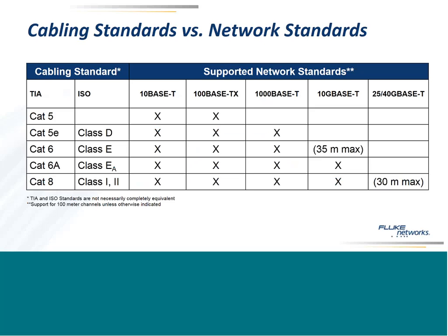It shows you the cabling standards. Now, as I mentioned, ISO and TIA generally work pretty close together. The standards I've put here on the same row aren't exactly the same, but they're pretty darn close. And for most people, you really don't need to notice the difference. So for example, Cat5 was pretty much designed to support 10Base-T and 100Base-TX. You can run 10Base-T on Cat3, but I don't even know if anybody makes that anymore. Cat5e came along, and it was designed to support 1000Base-T, or gigabit Ethernet over twisted pair. That's also ISO Class D.